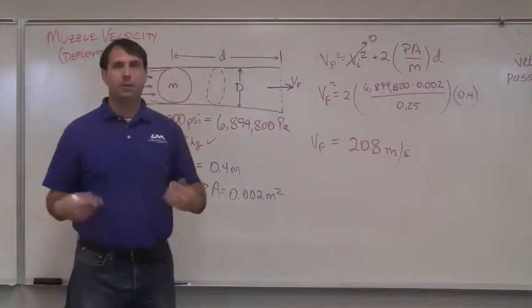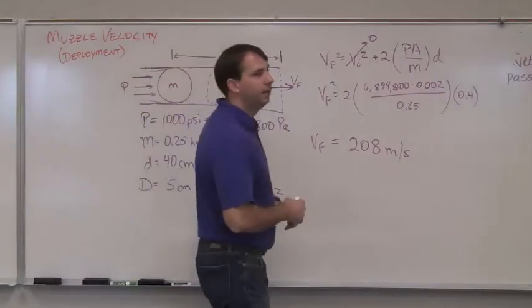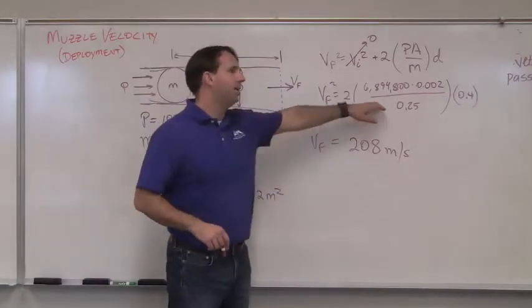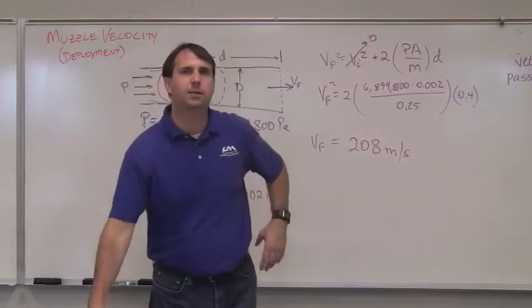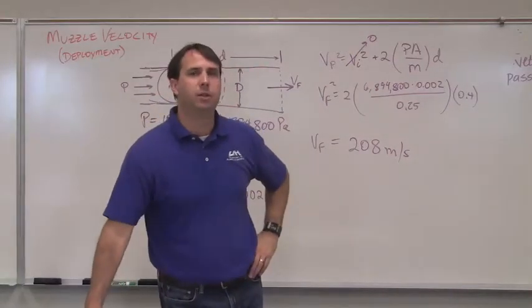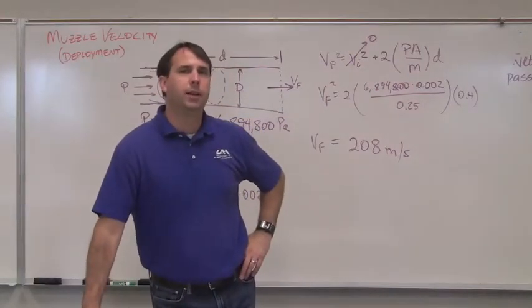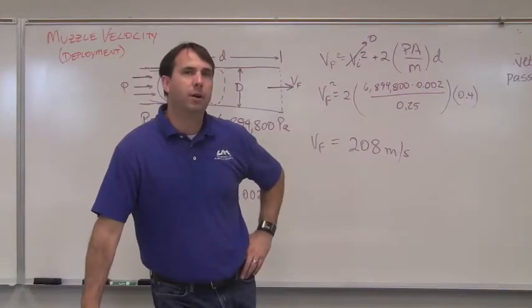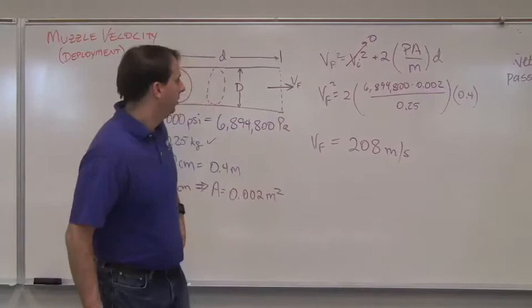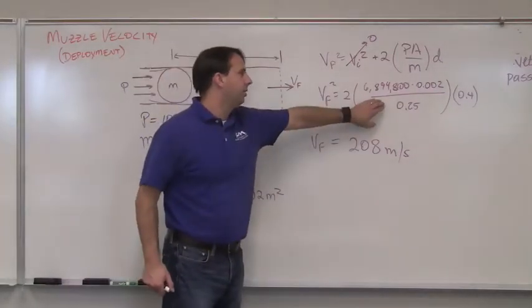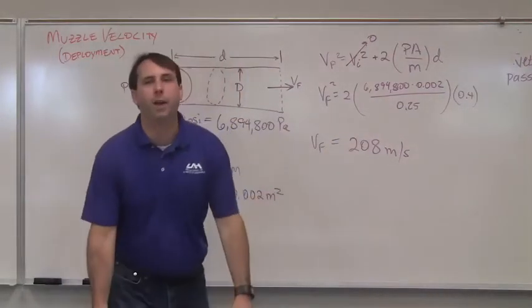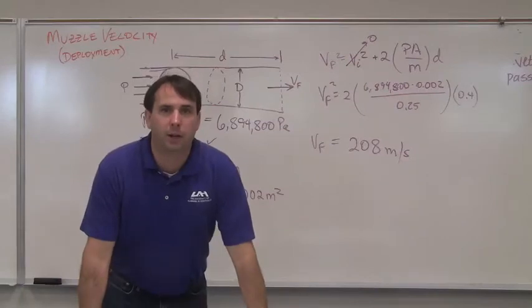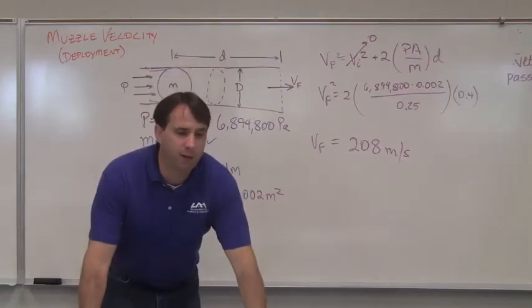If you just take that acceleration and divide it by 9.81, or divide it by 10 is close enough, that gives you how many G's it feels, if your probe is listed as being able to tolerate so many G's. A G is just 1 Earth gravity basically. So you just divide it by that. So here's your acceleration term if you want to figure out how fast your probe is accelerating. Pretty quick, by the way, so just check that out.